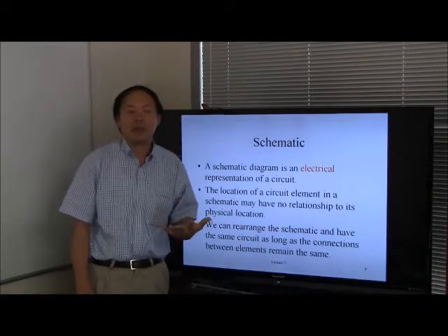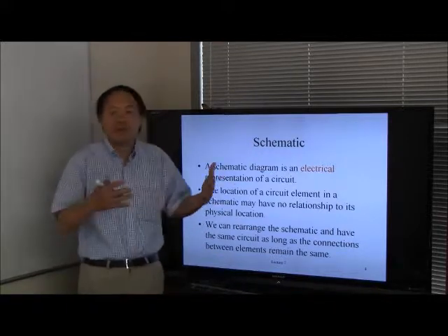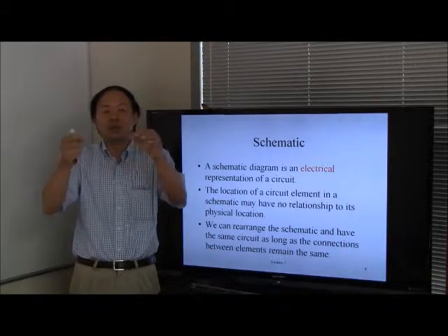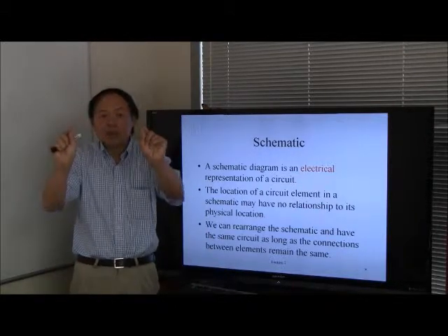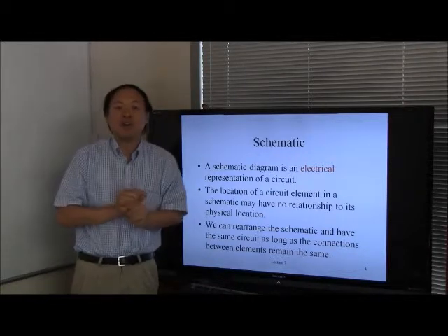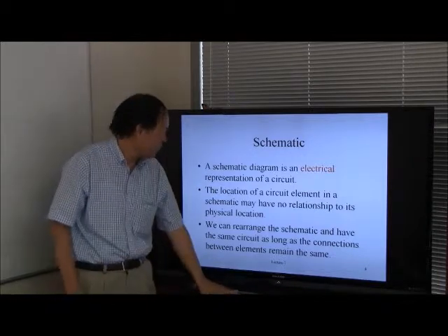So in PSpice, which is a very popular tool to enter schematics for a circuit, very often you first define the elements, and then most elements have 2 ends to it, and then you connect one end to another end of another element. So that's how you would define a circuit.